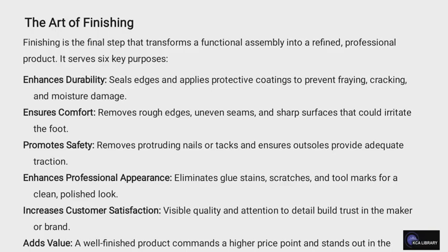These are the key purposes of finishing, where durability is being enhanced, and for comfort, it removes rough edges, uneven seams, and shapes surfaces that could irritate the foot. For safety, it removes protruding nails or tacks, and also provides adequate traction. For enhancing professional appearance, it eliminates glue stains, scratches, and tool marks for a clean, polished look. It's also visible quality and attention to detail, which builds trust in the maker or the brand.